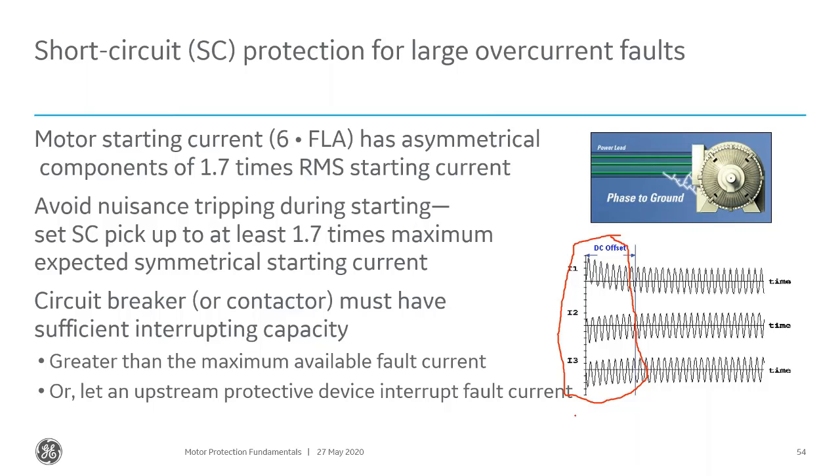If we think about what a contactor circuit looks like, there's my pen. A contactor circuit looks like this. There's some sort of elaborate control, there's a contactor, and then I've got my motor, right? This thing that's right here is a fuse. And that fuse is really meant to protect the motor for phase-to-phase faults.